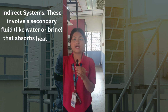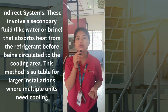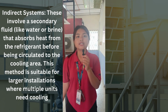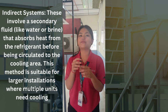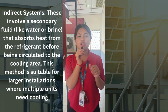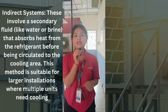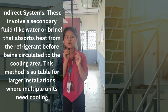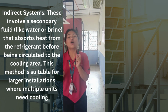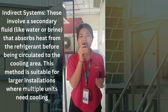Indirect system: a secondary fluid such as water or brine is used. This secondary fluid absorbs heat from the refrigerant first before it's circulated to the cooling area. This method is typically used for large installations like factories, shopping malls, or large commercial buildings where multiple units require cooling at the same time. Although the system is more complex, it is more efficient for large-scale operation.